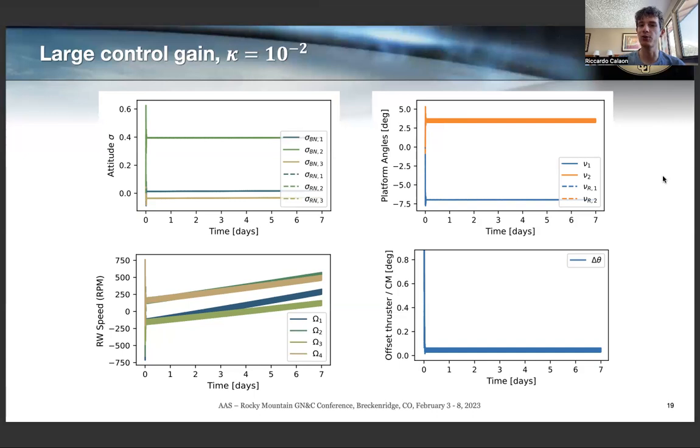And this affects also the attitude reference generation, which causes the attitude to never be able to converge and stabilize, which also has an impact on reaction wheels, which are constantly being actuated to track an attitude reference that can never be tracked. Bottom line is, if we choose a gain that is too large, it becomes impossible for this problem to converge. And this is just to highlight how Basilisk is very good at highlighting all these deeply interconnected phenomena that appear in such a complex simulation.